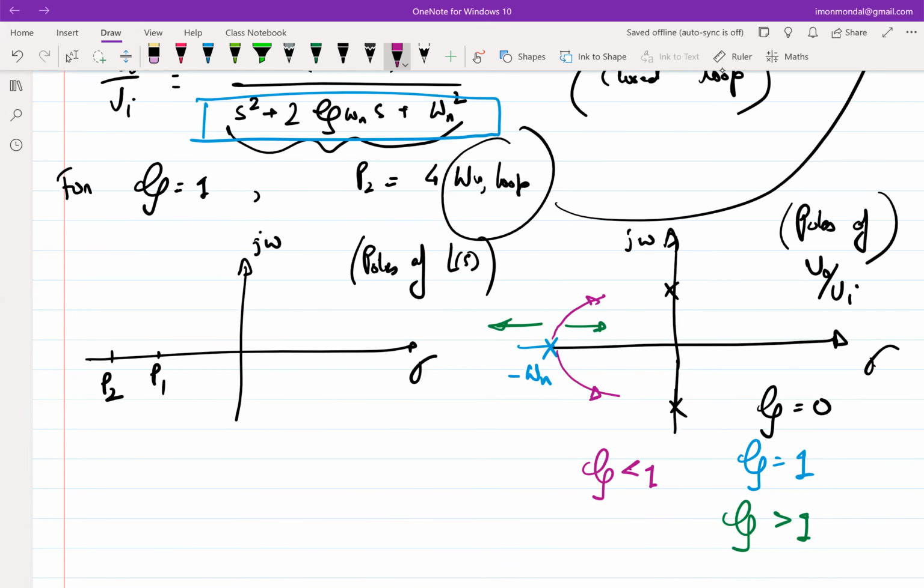This will do something like that. The reason I'm saying all these things is because you see the locus of the root, right? The movement of the root as you change zeta is going from being all real to imaginary, towards instability. And if it ever crosses this side, you're dead, right? But fortunately, in the case of second order systems, it's not a problem. It never crosses over. Zeta equal to 0 is the minimum. It doesn't really go beyond that.